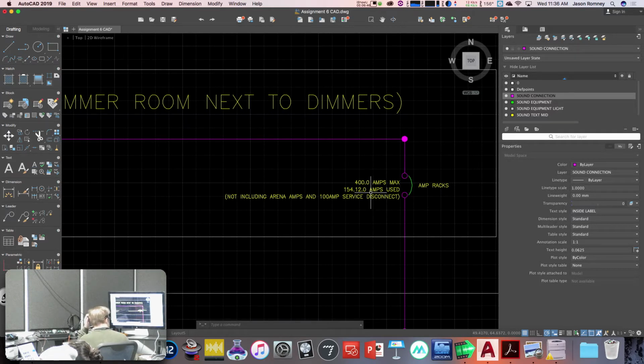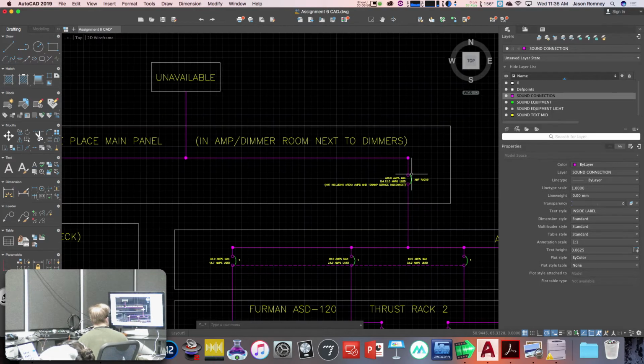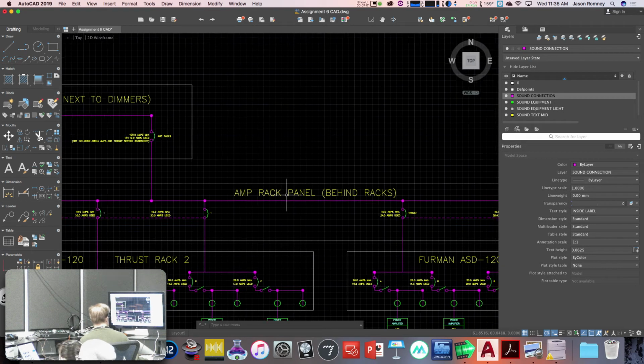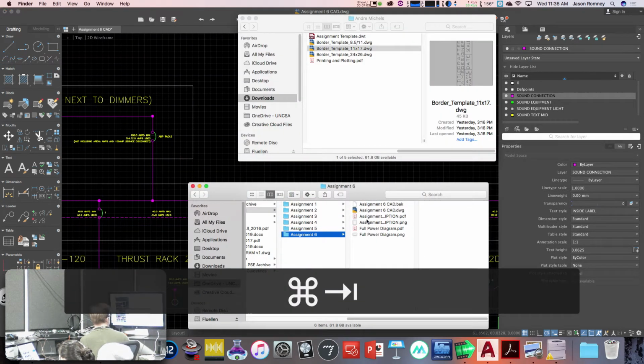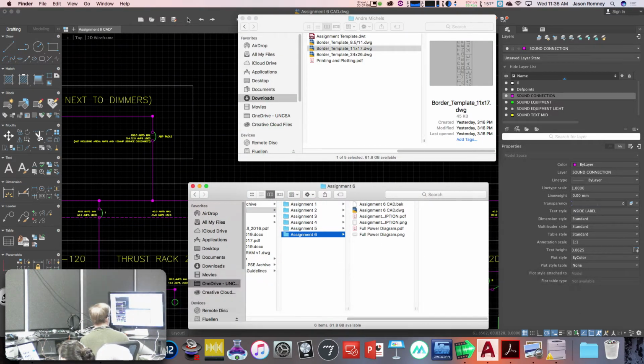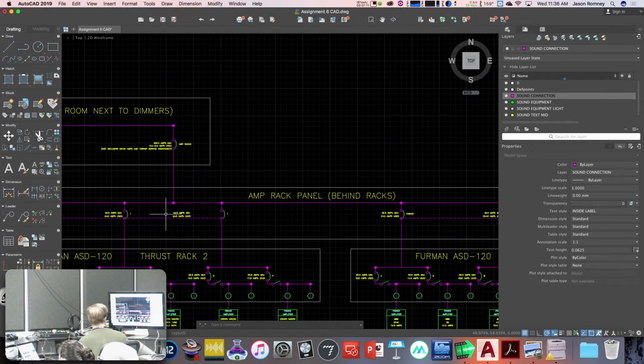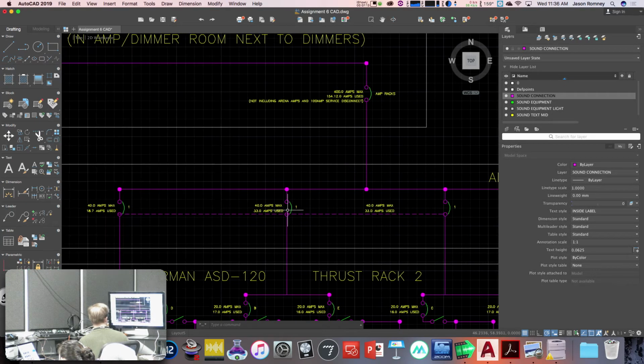So that's 400 amps. Now this breaker actually feeds an entire second panel, and that second panel is here, this amp rack panel, and this has more breakers on it. Let's see if my photos came yet. No, not yet. So it's 400 amps, but then it's got a bunch of these three-way 40 amp breakers that feed different power distribution units across both the Catawba and the Friedman.